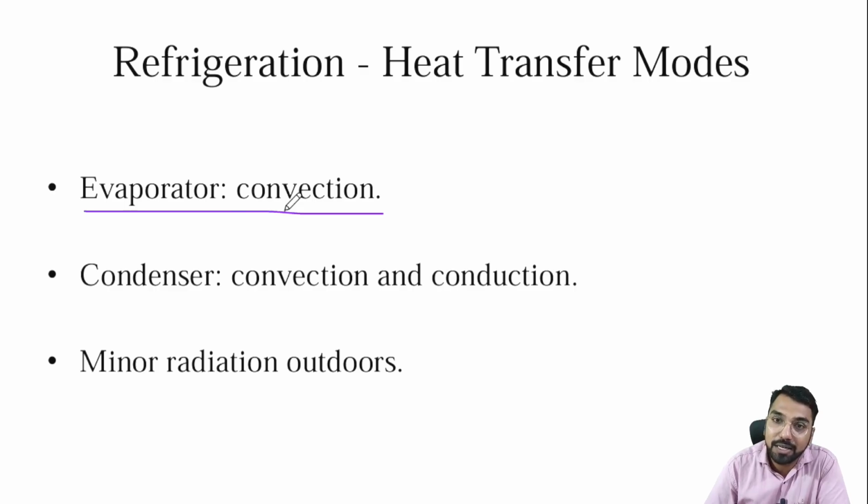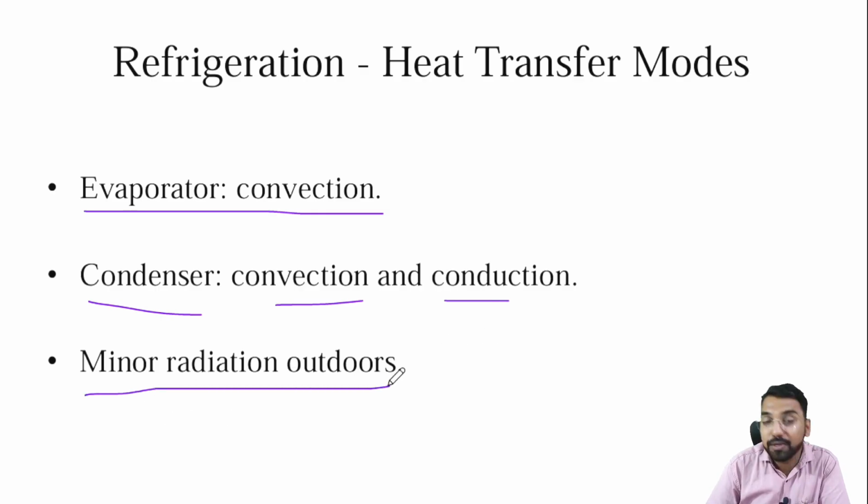And what is convection heat transfer? The fluid flows over the solid surface, and here the solid surface is the evaporator and the fluid is the surrounding medium. In the condenser, convection and conduction both happen together. Likewise, in the first lecture I gave the example of a cooling tower. In a condenser, convection and conduction both occur simultaneously, and there is minor radiation outwards.